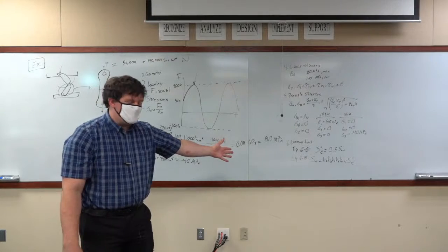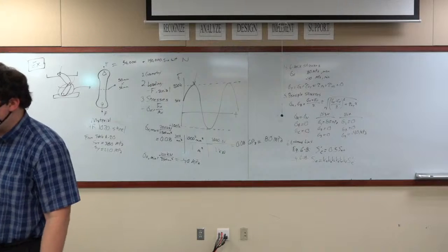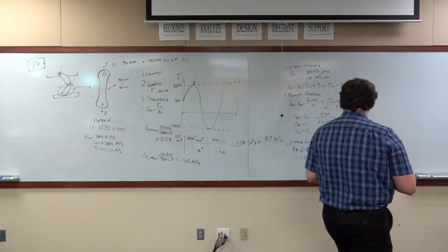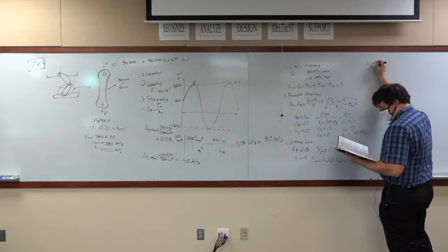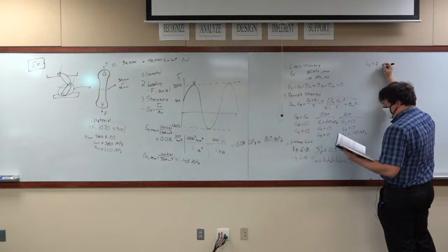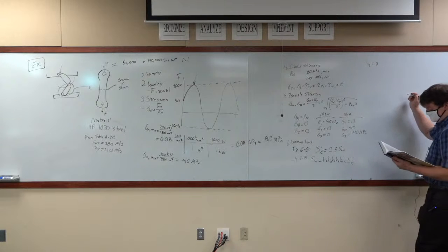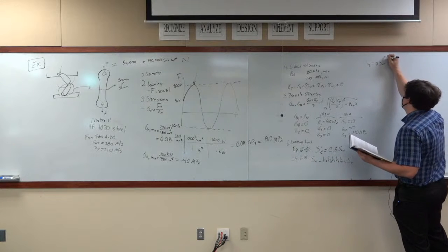All right, we have our formulas now. Now we just have to go through and figure out what is Ka, what is Kb, what is Kc. Well, Ka, this is the surface factor. It depends on the condition of the surface of the material. The surface of the material oftentimes will have cracks on it or in it. That's where a lot of disparities come in. So yes, this strongly correlates with the overall endurance limit in fatigue.